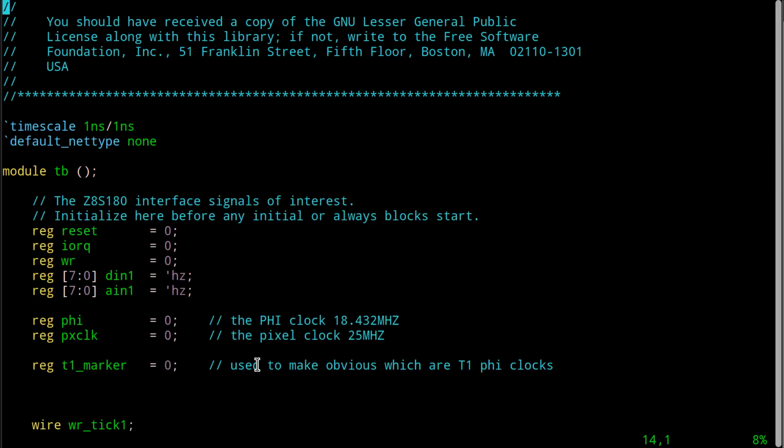It should flow through all these modules and get them into a known working state, even if I don't preset all these things, okay? And if you think about it, you need that anyway, because when you run it on a real FPGA and it wakes up, yes, it'll wake up in a consistent state because an FPGA is really a RAM device and all these things have values all the time.